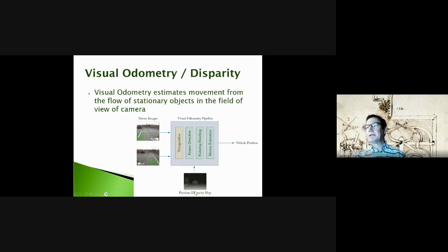But the idea is that you've got some previous frame that you've stored, and now you try to match features between this disparity map, and once you process these two images, you're going to have a disparity map here. You try to pick out the same features, right, and match those features, right?